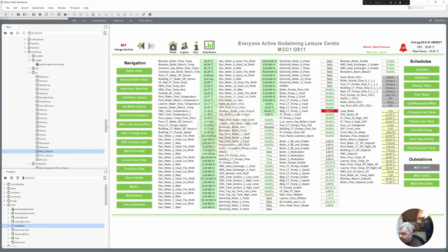Just to show you, on the BACnet points, I have put a history on every single point coming in, as well as alarms, because you've got to understand you've got your Trend IQ3 or IQ4 system going to a Tridium Niagara controller, which is just collecting the points to then send via Niagara. So on the Tridium Niagara controller, I will put the alarms for each point that requires an alarm, and every sensor I will put a history on.